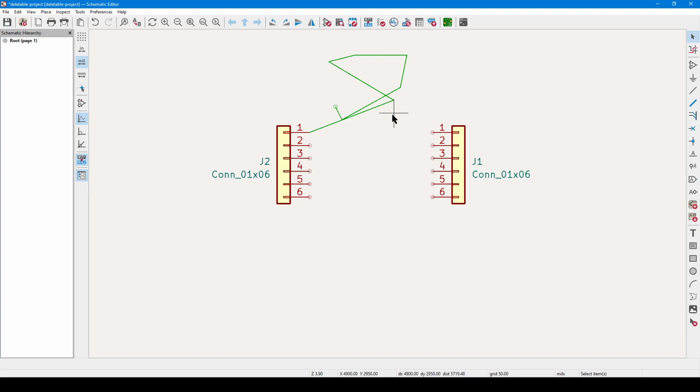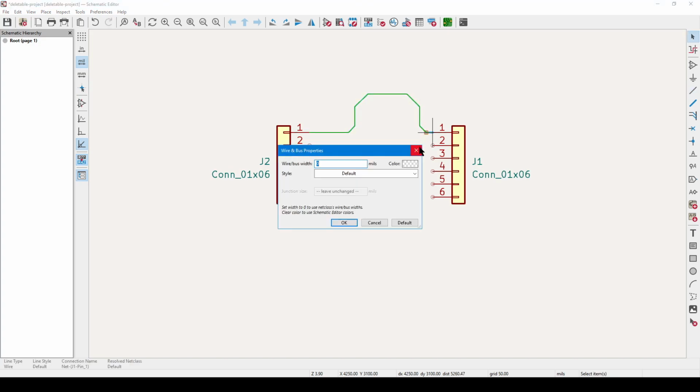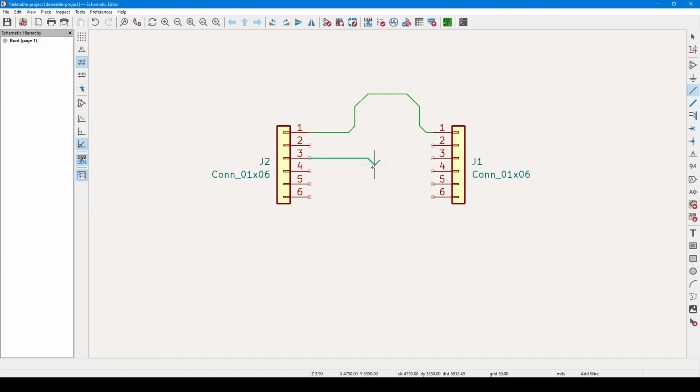This can also lead to things looking connected when in reality they aren't connected at all. Finally, we have 45-degree mode. This will let you angle your wires in 45-degree steps, and in my opinion this is a good compromise. Very often I use this mode if I want to draw a crossover. And that concludes wires and nets.